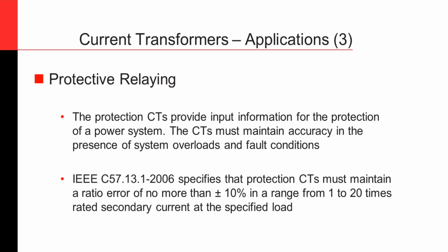Another example that I can think of off the top of my head is when you charge a transformer. It's a general industry practice that when you charge a transformer, the current flowing through the transformer is anywhere between 5 to 15 times the rated current during the initial cycle. That's the transient current consumed by the transformer itself.